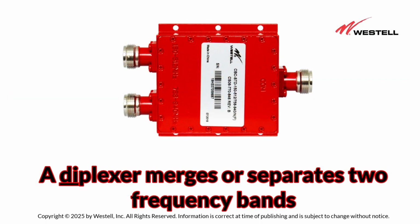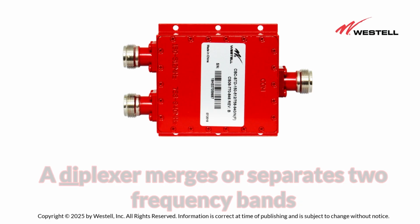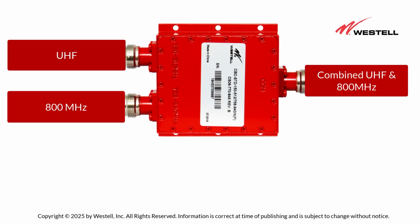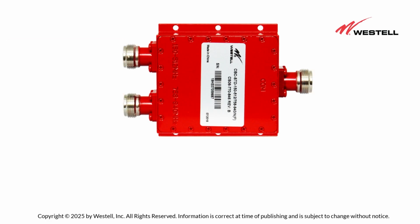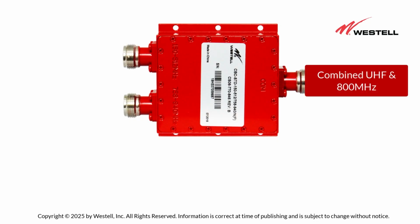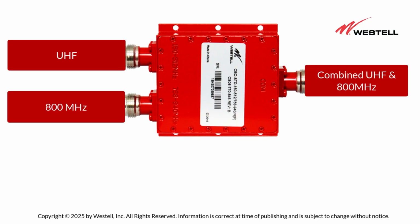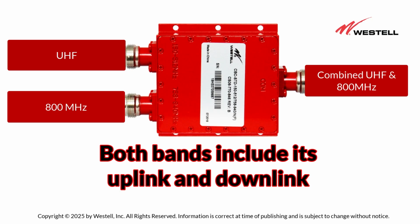A diplexer, on the other hand, either combines or separates two different frequency bands using low-pass, high-pass, or bandpass filters. It isolates distinct frequency bands from each other. For example, a diplexer with two inputs, one for UHF and another for 800 MHz, can combine these into a single output. When the process is reversed, it can take in combined signals from UHF and 800 MHz and separate them into separate outputs. Each band's output includes both its uplink and downlink bands.